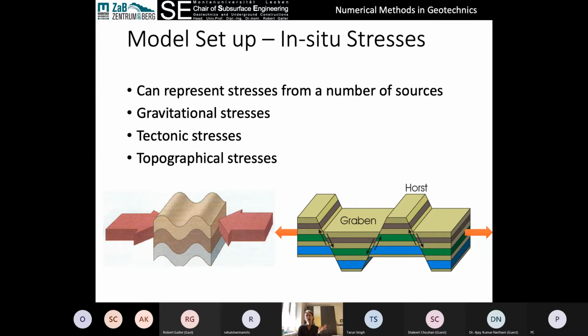You also have to consider topography. In a mountain area, even if you're just doing a tunnel punching through a shoulder of a mountain that's only 300 meters deep, the stress orientation is going to be governed by the topography. Sigma 1 is often parallel to the slope of a hill, so it will not be perfectly vertical.